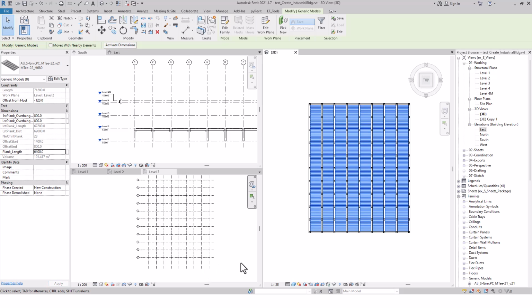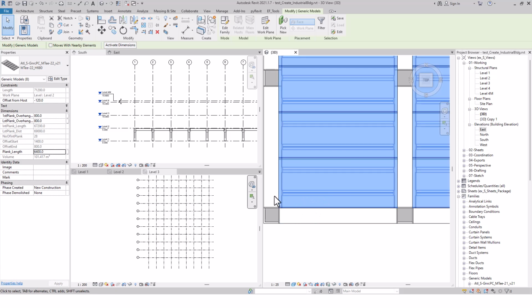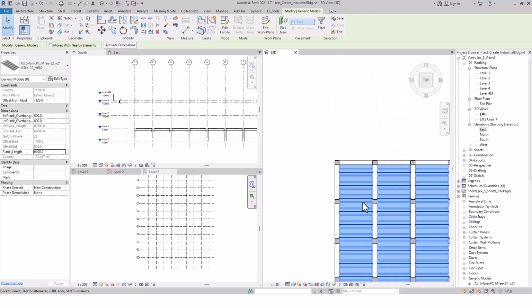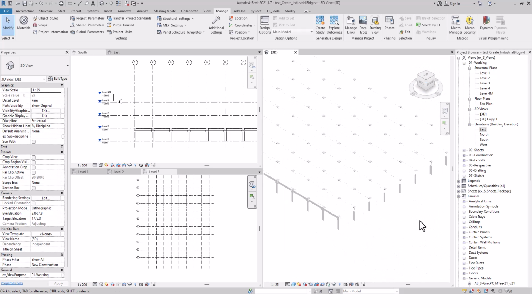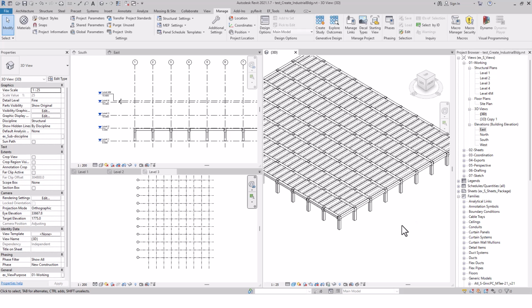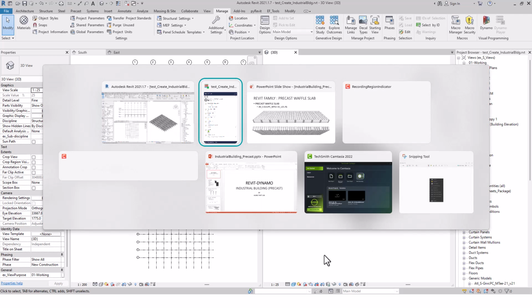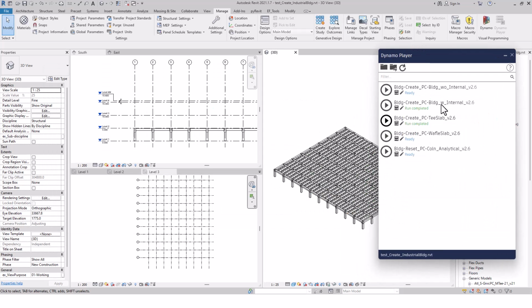it. Then we can see that those T-planks are nicely placed within the horizontal beams and within the vertical beams as well. There are no gaps. So then we are done with placing the T-slab, right? Okay, so now we have done 2 steps, so now we are going to create another level. So go back to the Dynamo player, same thing, go back and check the PC building with the internet again.